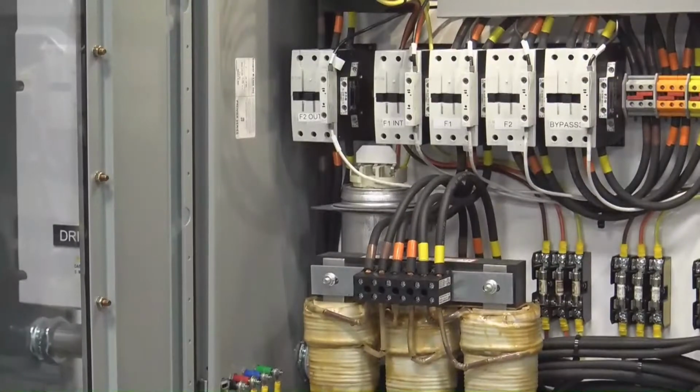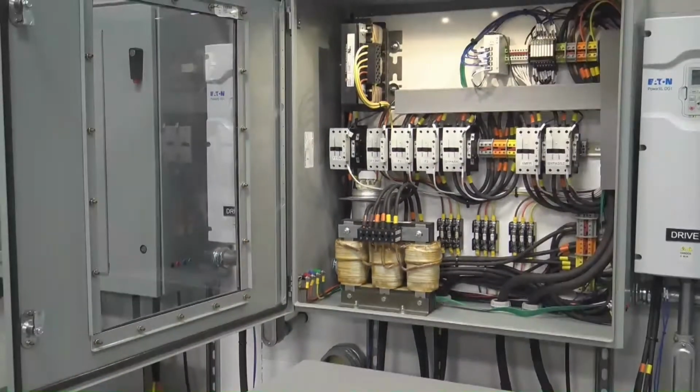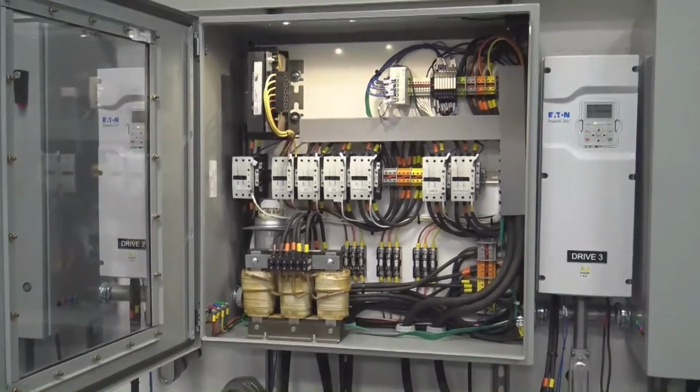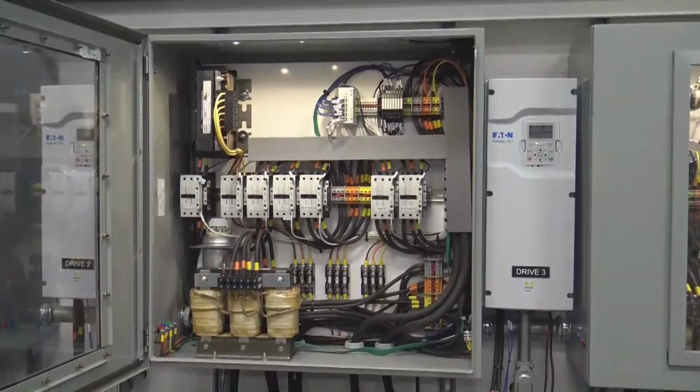All the other contactors and everything in there are for part of our demo, but we also have a contactor to be able to remove the capacitor outside of that, because if you do have a capacitor, what can happen is that capacitor at a very light load will look like power factor correction and maybe raise the voltage. So when that drive dedicated filter doesn't have a load on it, that capacitor acts to raise voltage.